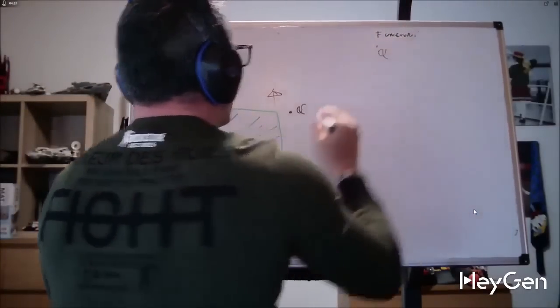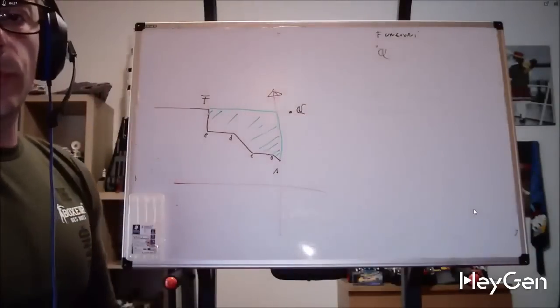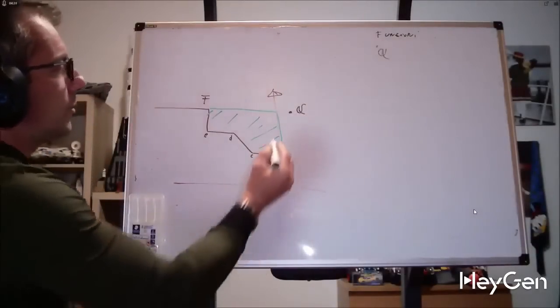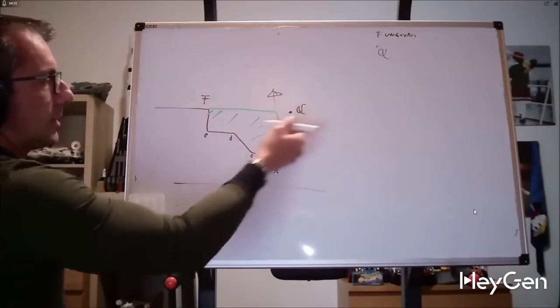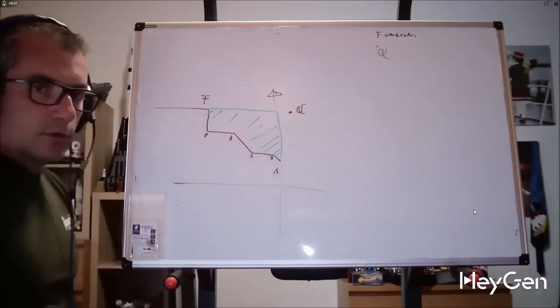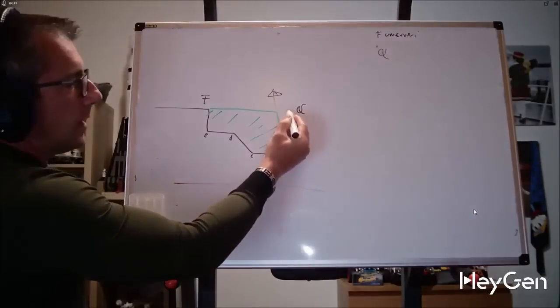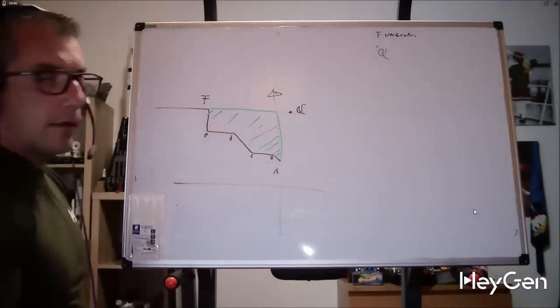Point alpha simply tells the machine where the furthest and safest edge of the piece is located. So point alpha will be, for a macro that involves longitudinal machining, coinciding with the outer diameter of the piece, and at 2 or 3 millimeters of safety in Z.